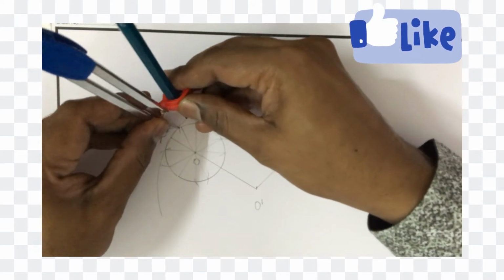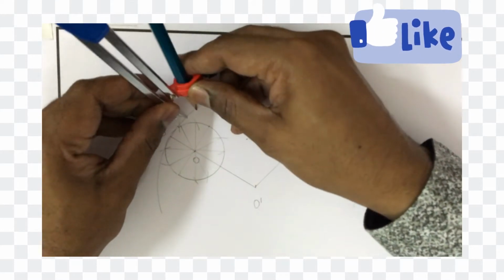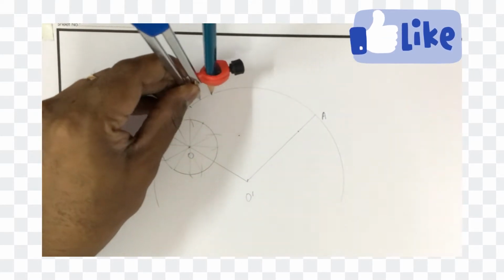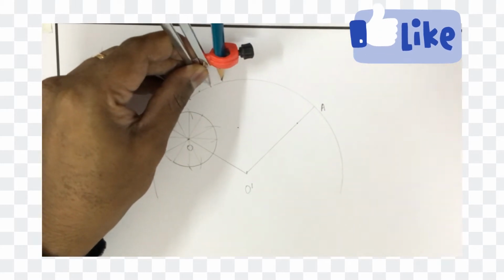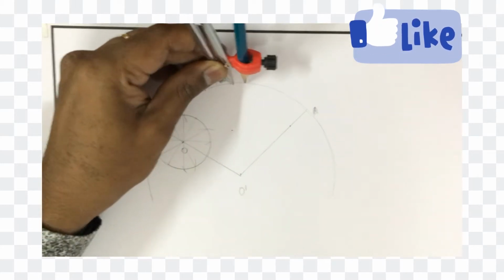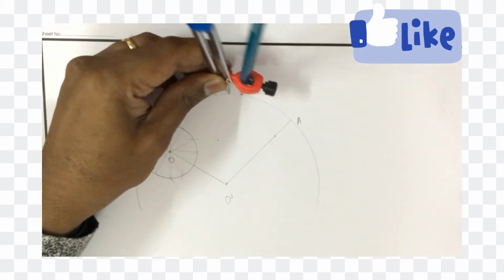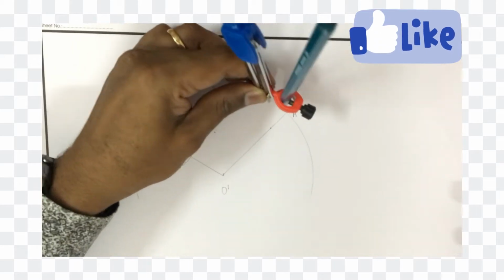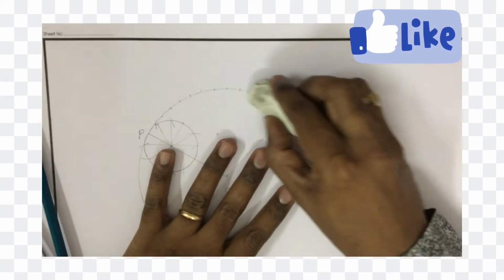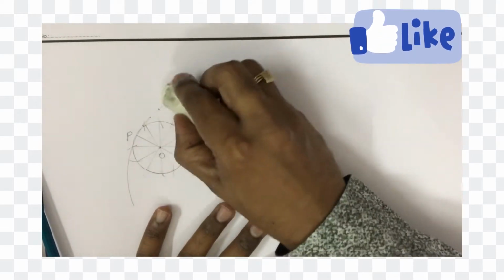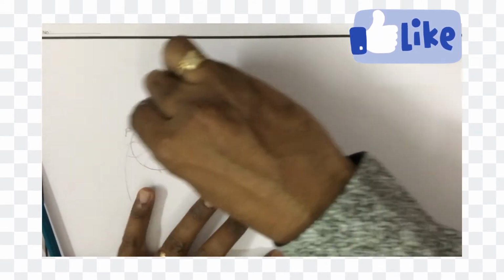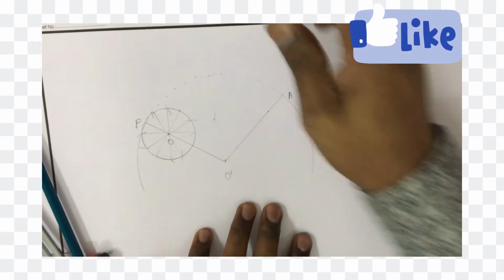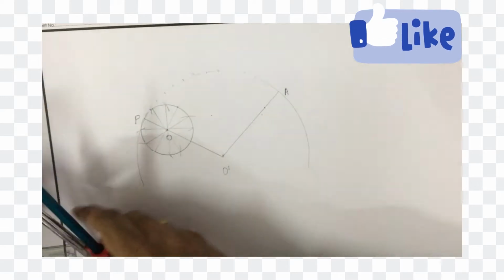Later this is 2. So on, cut this into 12 equal divisions: 3, 4, 5, 6, 7, 8, 9, 10, 11, 12. So it is not exact. So what I am going to do here is I am going to erase this and take the length a bit increased in size. Then I am going to work out the trial and error method to get it into 12 equal divisions.